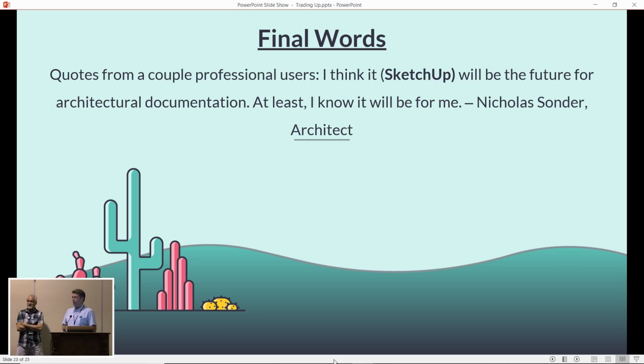Yes, you just have to know what to give them and what they're going to be looking for. And actually, in some cases, I get compliments that they like what they get from me better than from other architects, because they'll get this giant file, like a site plan. Our surveyors like to lay out the foundation on the site, and so they'll ask, I need your site plan so I can go out and survey all the building corners and the driveway. So I go into SketchUp, and on my site plan I isolate the property line, the building footprint, and the driveway, and that's it. Then I export that as an AutoCAD file out of SketchUp, and they love that file because it's easy. It's like 65 kilobytes, and they're done.